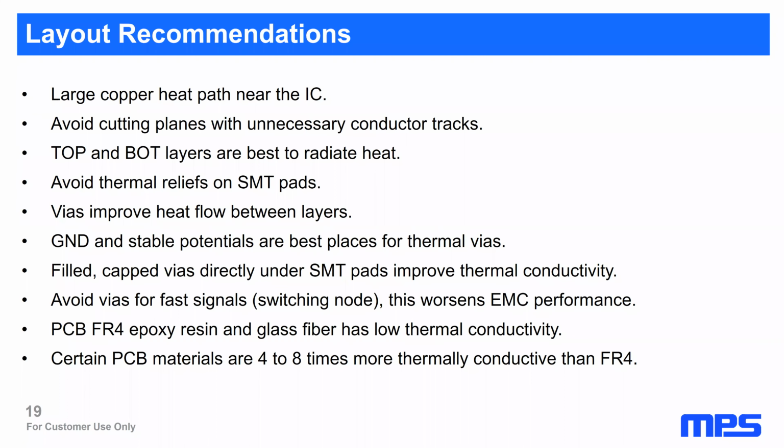Layout recommendations: large copper heat path near the IC. Avoid cutting planes with unnecessary conductor tracks. That means don't route any other wires directly to the IC. You will cut the very good heatsink of the top layer.